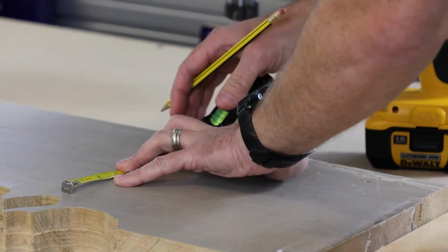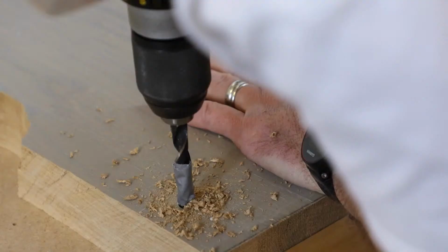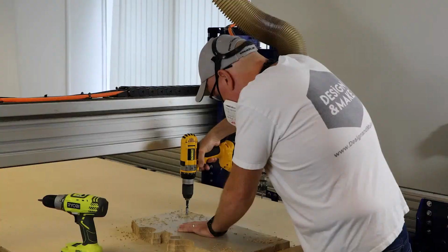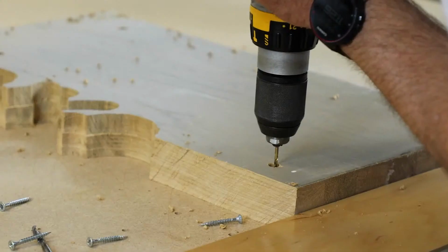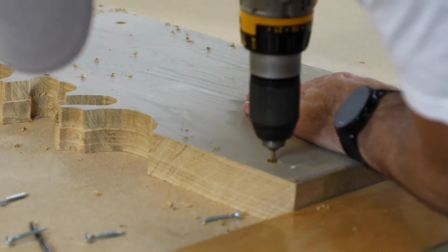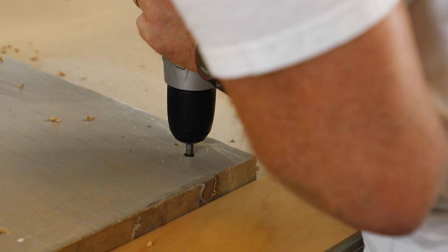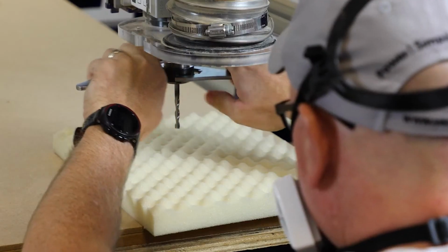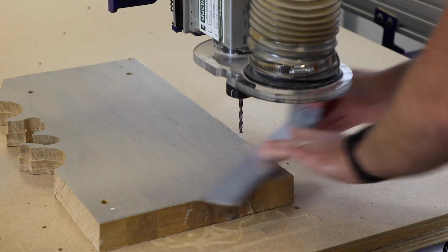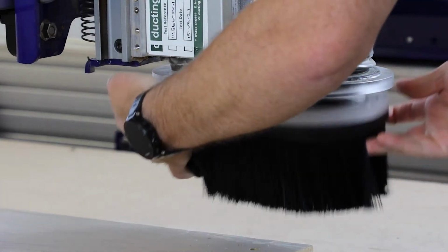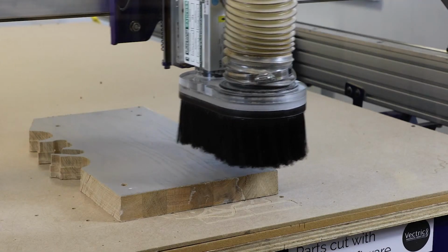Out of all the parts we're going to cut for this project, this one made me the most nervous. First of all, the material is really thick, it's really hard, so I had to make sure that I had good tools and a good hold down method. So I went ahead and countersunk all of my screw holes, and then went in with my smaller drill bit and pre-drilled the holes so I could get those screws in nice and easily. And I also had to make sure I had long enough bits so that I wouldn't end up breaking them by mistake or bottoming out on the collet, which would be terrible.